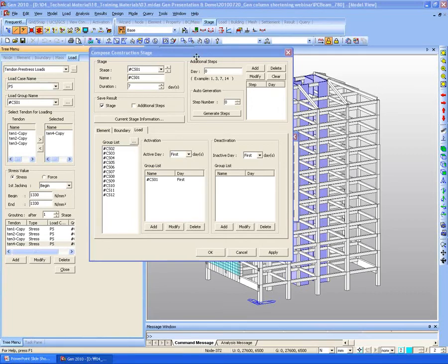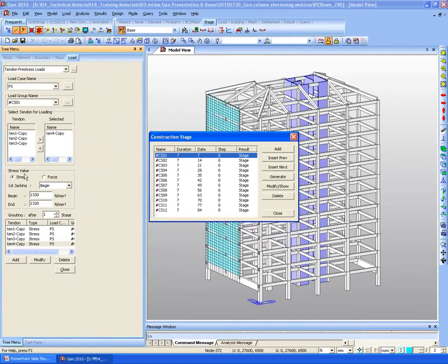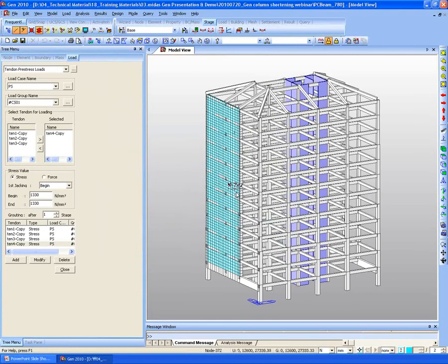The other question is whether it's possible to use the wall element in this position, where the load will be distributed to the transfer beam. We can use any type of element. In order to show you that both are available, I entered two different element types here. So even though you enter the walls here, we can consider them as well during the construction stages.